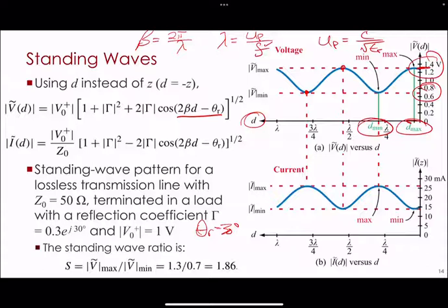And to go back to that example, if you're looking for that antenna and you look up the data sheet, they're definitely going to have the voltage standing wave ratio. And there's really like 2 numbers that everyone goes by. For a standing wave ratio, almost everyone defines a working antenna, or an adequate antenna, as when the standing wave ratio is either less than 2 or less than 3.